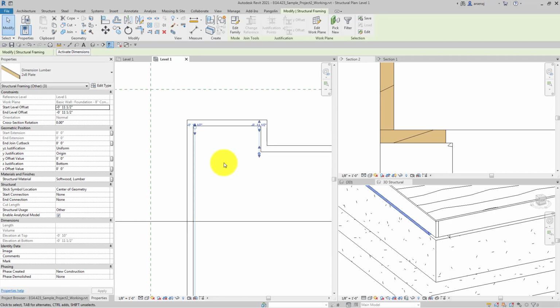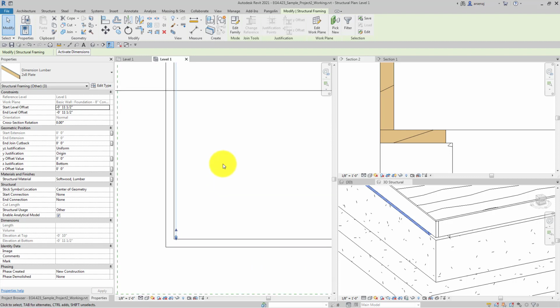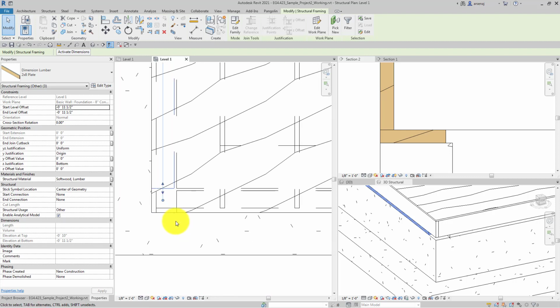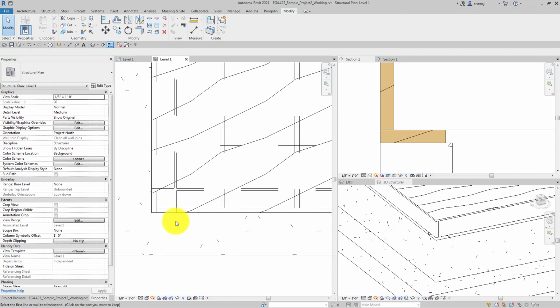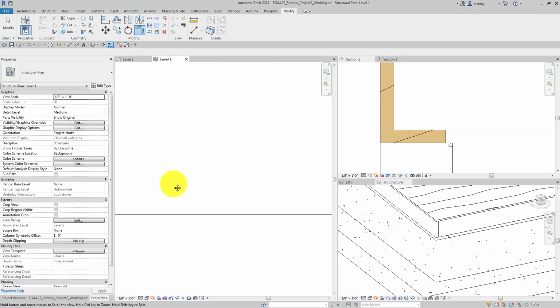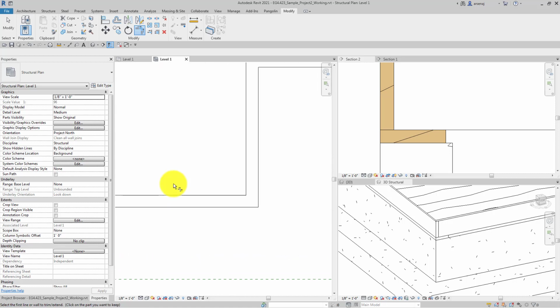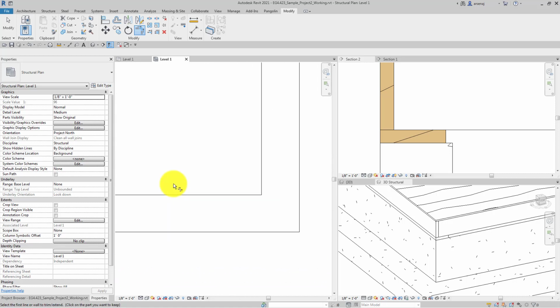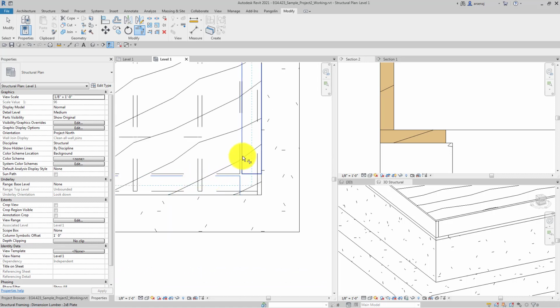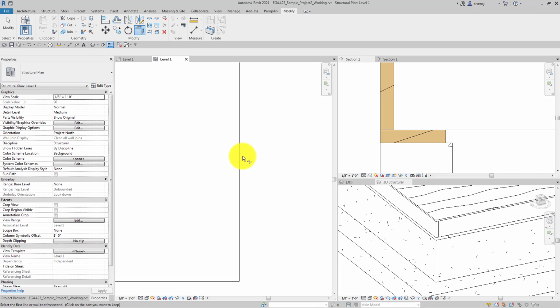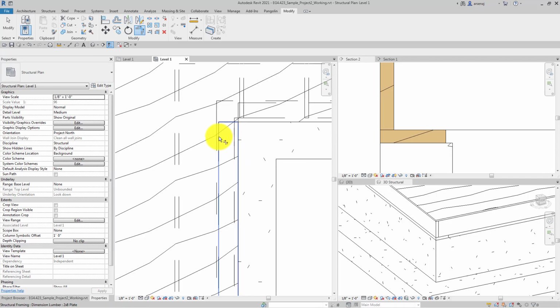And as we go through and do that, you can see that it's actually putting it back into a linked chain of beams, or in this case the beam is a top plate. So one of the things you could have done is done this process first, gone through and trimmed, but either way we would have to either offset or trim first.